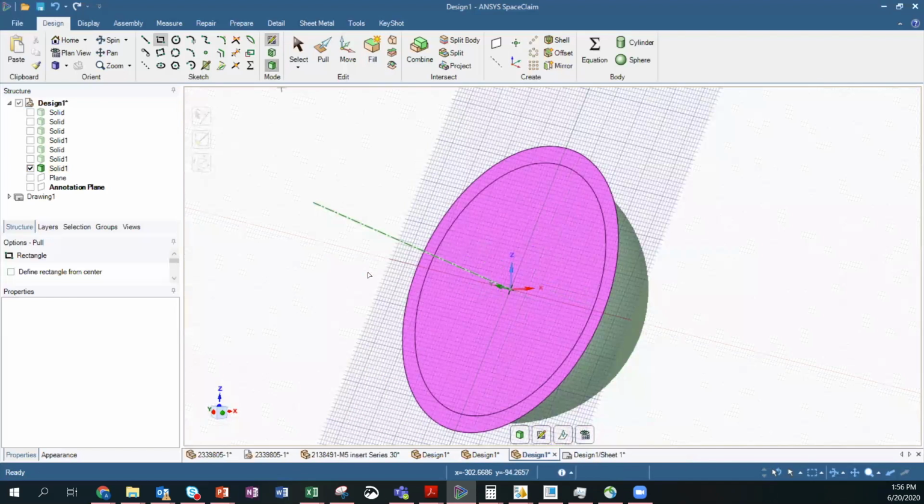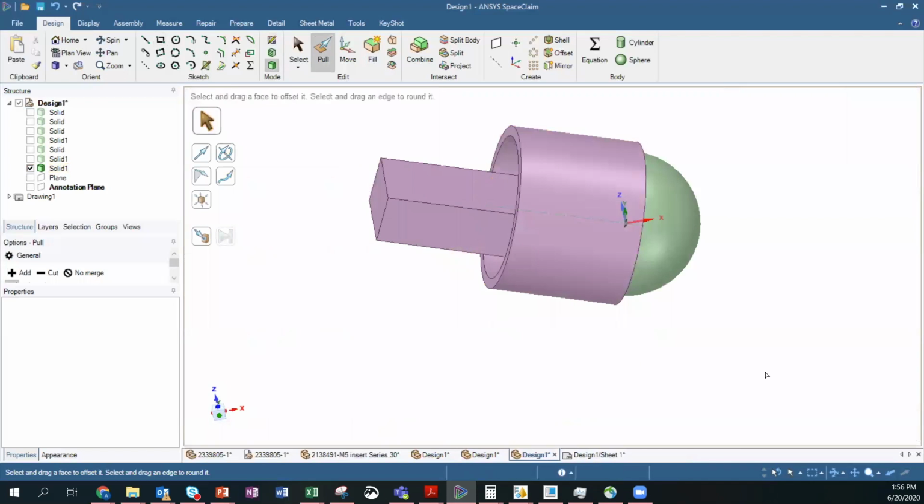So this is the design. The plastic has to be melted and flowed in this. So PBT, you can easily flow it. The reason is the temperature at which you can flow is like 160 degrees Celsius. So it's easy to flow. Whereas if you see nylon, nylon requires 350 degrees Celsius to flow it. So it will be a little difficult for the manufacturers to do it, but it's doable. We all have nylon and everything. So we stick with PBT. If not, we go for nylon.